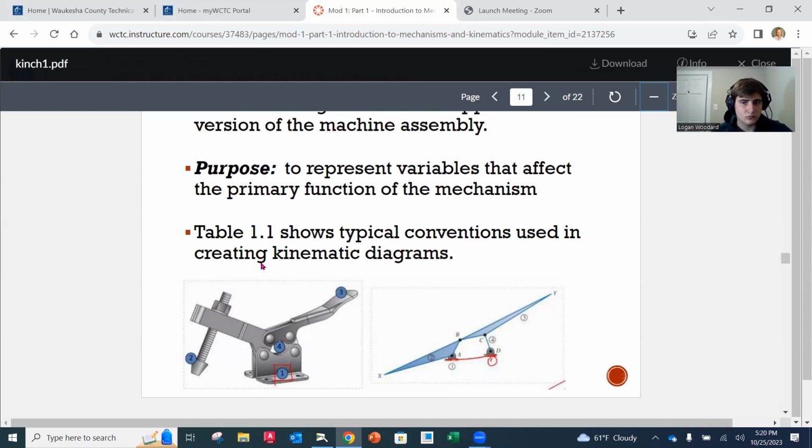As you get into these things and you're the designer for them, it'll become more apparent what you're most interested in. Because a lot of times, when we're in that kinematic analysis stage, the layout work, we're going to be interested in what is the travel of these things? Are they going to interfere with something? Is there going to be any collisions that are going to occur? We may have to add a couple of additional special interest points to determine that.